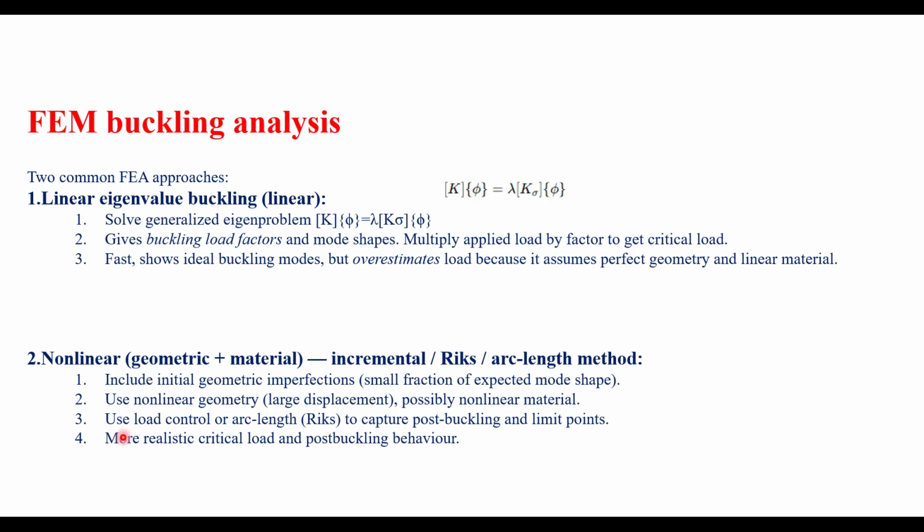Next, very important is this one, use of the control arc to capture the post buckling and the limit points. Let's say once we do the validations by using the material and the geometric nonlinearities, we'll draw a curve. With that curve we'll get to know how exactly the buckling is happening, at what load case and at what displacement it is happening, and how much load factor it is considering. Let's say my model needs to pass exactly 50 kilonewton. If it is not passing for that, these all things we can predict by using the post processing.